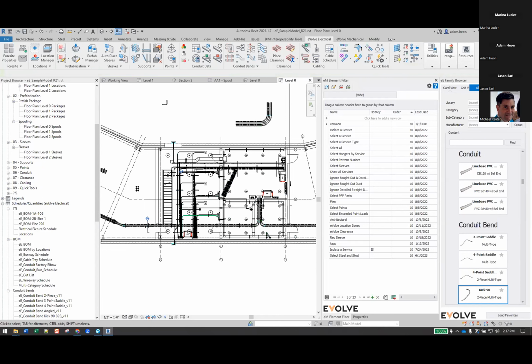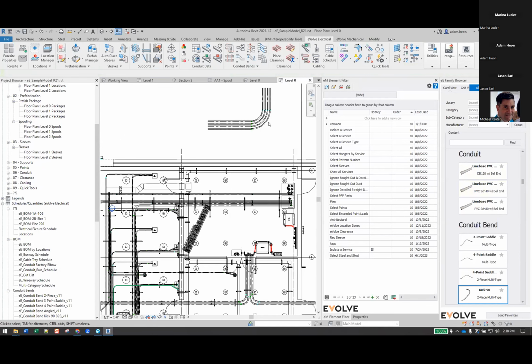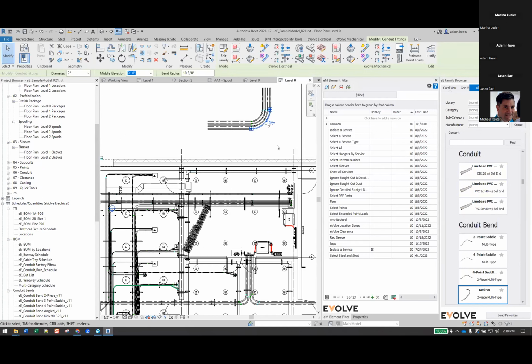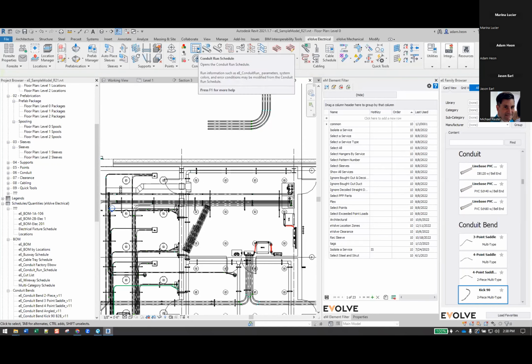Yeah, I think you can use a Revit schedule, versus the quick bend tool one by one. You should be able to schedule the angles by run. We are looking to improve the run schedule quite a bit, and looking at degrees and things like that would be in there. But today you'll have to do it through a Revit schedule or something.